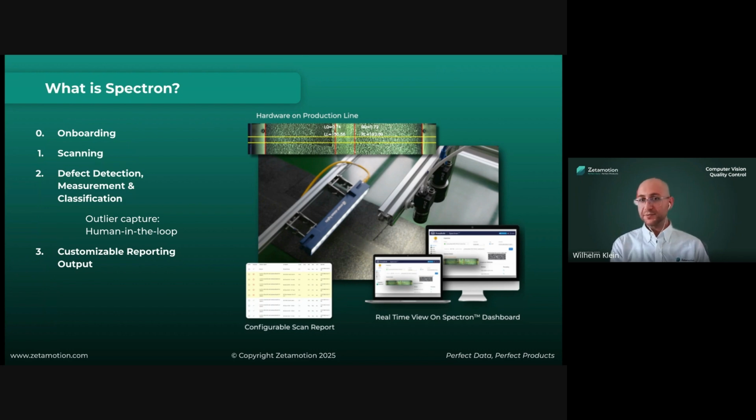It does the inspection itself, of course. It covers all sorts of parameters that you would have with a human inspector, so including not just anomaly detection and flagging, but really specified defect detection, classification, measurement, parameters like clustering, how many of what type can be in what area, what can be masked out, object verification, if there's items that need to be placed there, like certain markers or certain components, OCR reading, anything that is essentially anything that a human would do with his or her eyes or with a measurement tape or magnifying glass. The system is made to do.